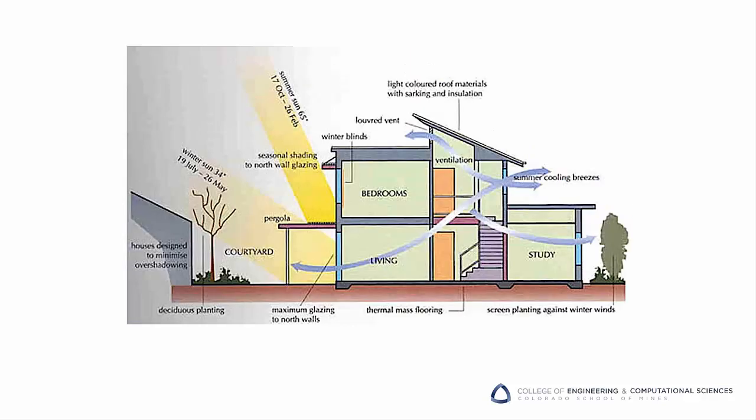spaces. This sample of a single-family residence shows a good example of how a home can be designed to maximize the use of vegetation, topology, and solar energy on a site. Notice the use of overhangs to control lighting. During the heat of the day, the overhangs provide protection from the sun, but allow late afternoon and winter sunlight into the space. In addition, trees are used as a screen to block winter winds, and deciduous trees are planted to block the summer sun.